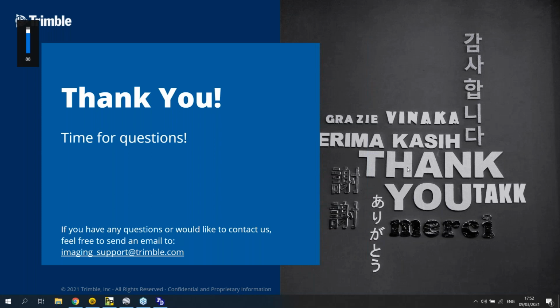The first question we received was about the MX2. What options do users of MX2 systems have in terms of processing data besides Trimble Trident? My understanding is that TBC is not compatible with MX2 data. Yes, that is correct. For MX2 data, Trident is a must. You will need to process your data first in Trident and do any data preparation there, such as registration, colorization, point cloud cleaning or removal of ghosts.